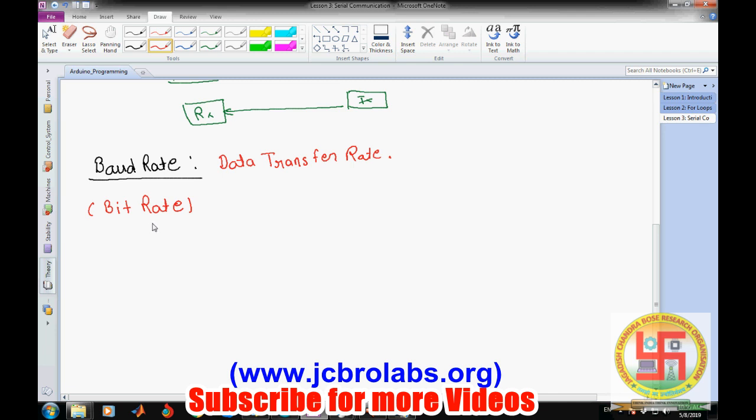transmitting per second. So let's say we are using a baud rate of QPSK, then within one level we are transmitting, let's say, 00, 01, 10, 11. So in a single level we are transmitting 2 bits, but in bit rate we will be transmitting 1 bit at a time. Okay, so don't confuse baud rate and bit rate.